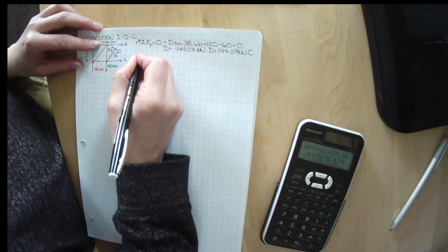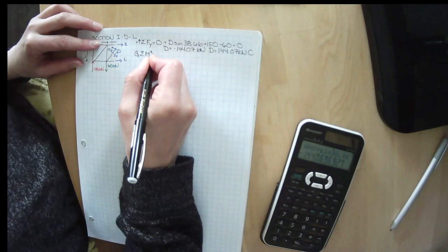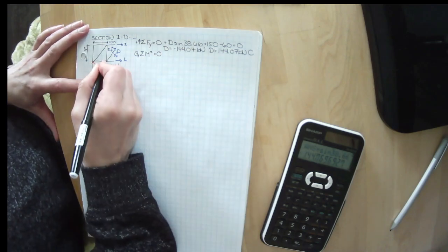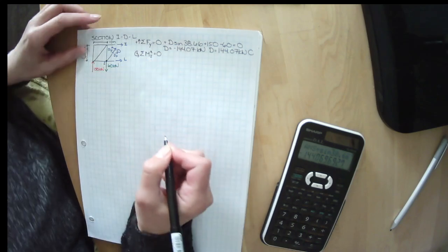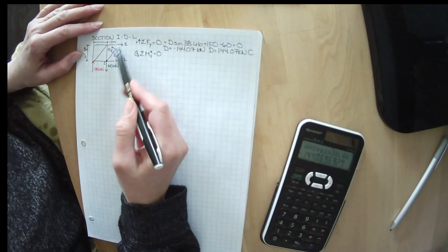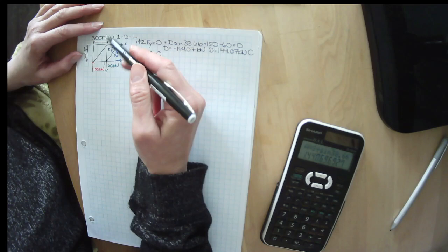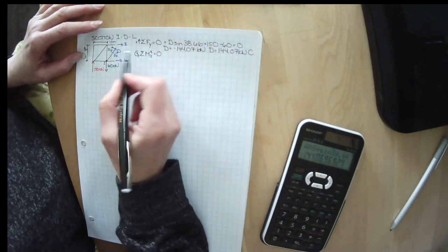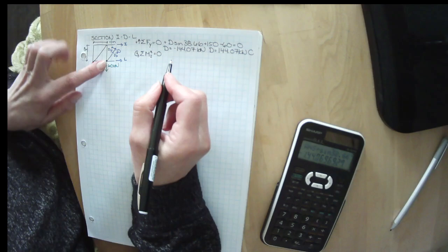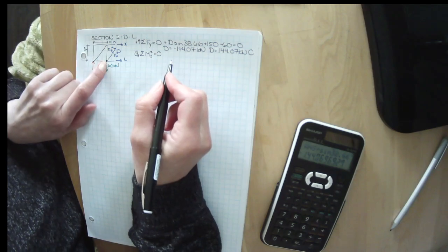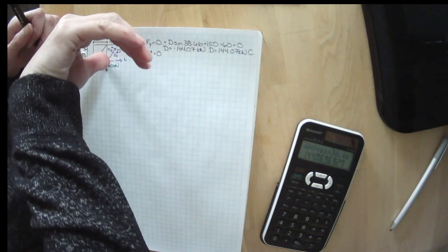We can sum the moments about the z-axis, where everything spinning in that direction is 0, and I am going to pick this node here, which is 0, 1, 2. I'm going to pick node 2 to spin this about. What I like about that is I don't have to deal with dx and dy. L goes right through it, and a 60 happens to go right through it. I end up with 150 and I both trying to spin this about node 2. I tries to spin it in this direction. If I use my right hand, that means it's negative.